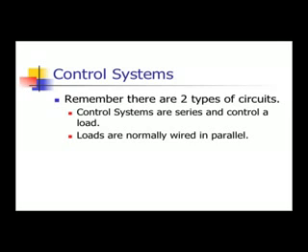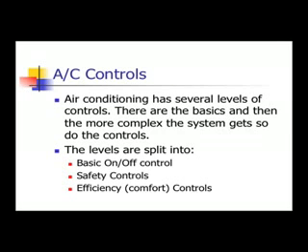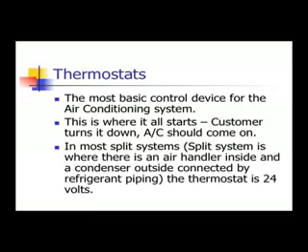It can signal heat, it can signal cool, it can deal with indoor blower fans, it can deal with compressors and condensers. Remember, there are two types of circuits. The control system are series and a load. Loads are normally wired in parallel.